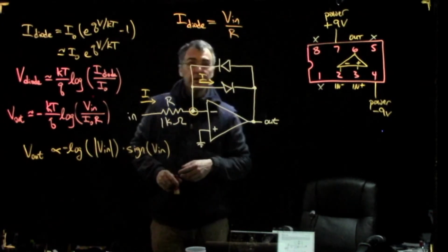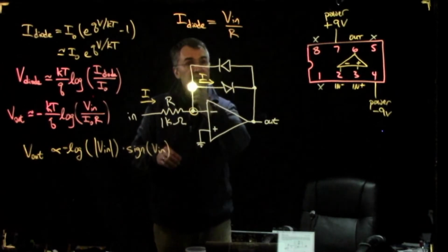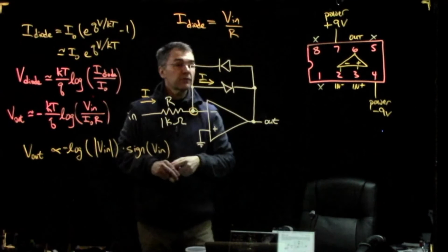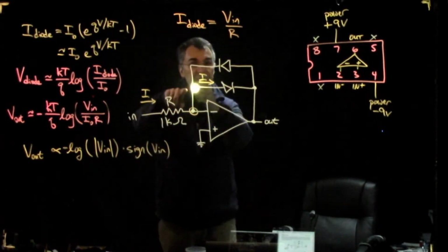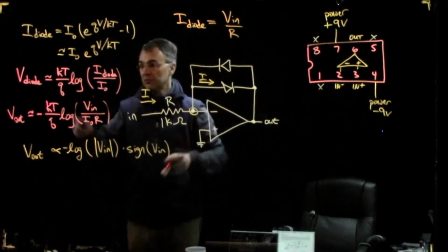Now, that's the diode drop, basically the left end minus the right end of this diode that we drew on the bottom. If this left end is at 0, then this right end is at a negative voltage. So that puts V out at a negative voltage.